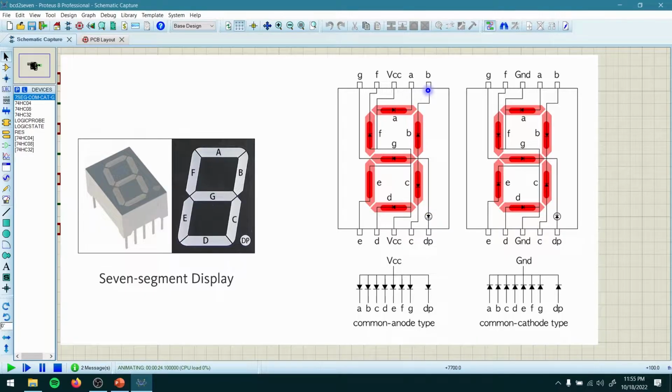Okay, so you can see the pin numbers here, and we have two VCCs here at the top here and also in the bottom. If I use one of them, that will be enough. And for the common cathode type, the ground or logic low should be common for all the LEDs. That means to drive an LED, you have to give logic high to that particular pin.